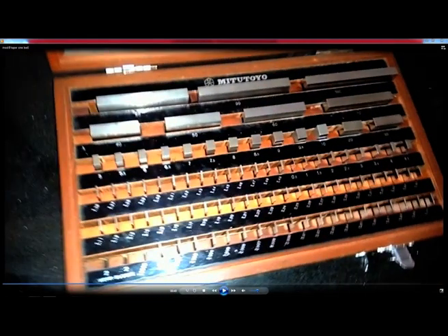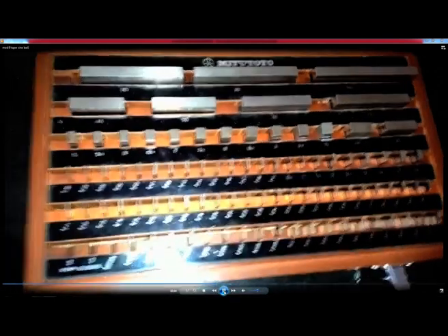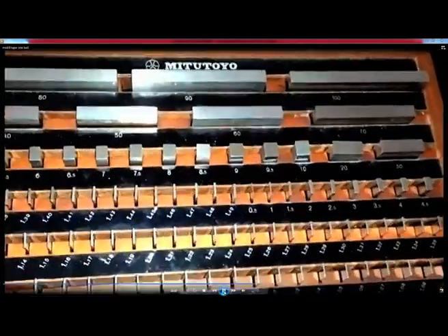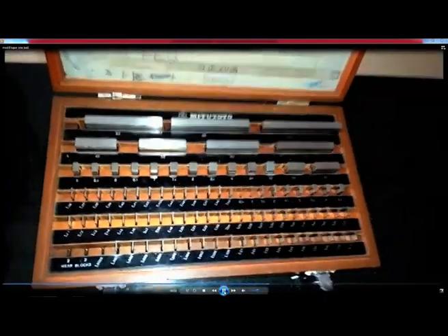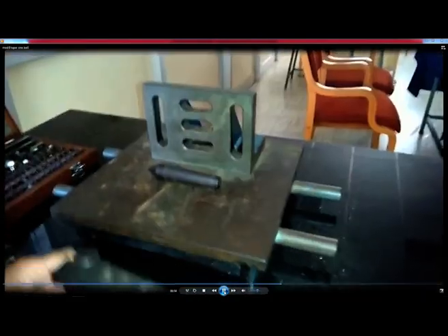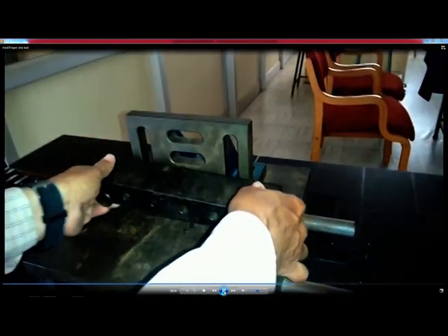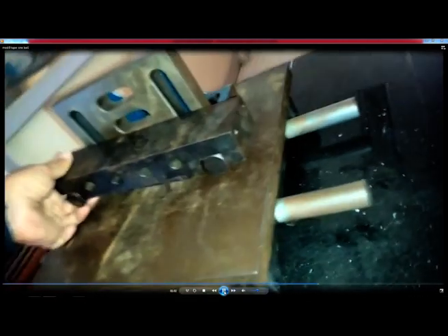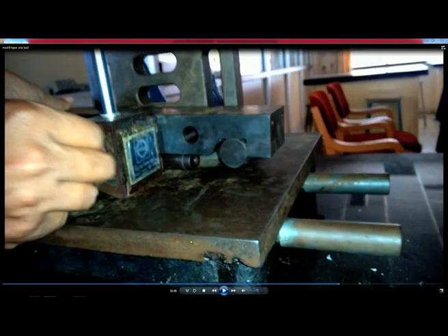We have the slip gauge box. Now, we have to mount the sine bar on the workpiece, that is the tapered component, and then we have to keep the magnetic stand in front of the sine bar so that it will not fall.